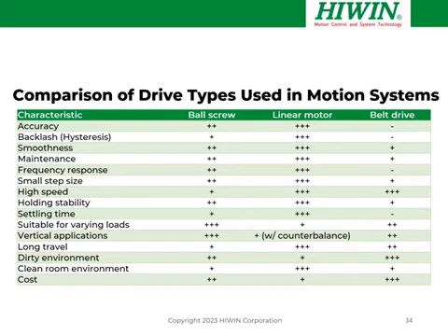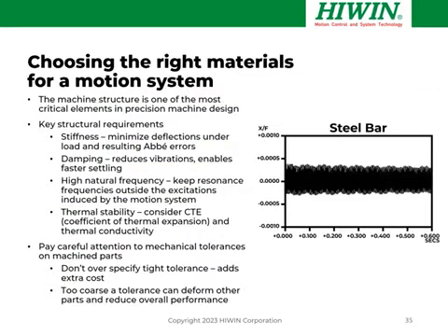Another type of drive is the belt drive. We're not going to really dwell on it here because they're not really used in high precision motion systems. It's less precise than a ball screw or a linear motor, but it's worth considering for certain applications. Low cost, low accuracy mainly, but they're very good for high speed as well, and they work well in dirty environments.